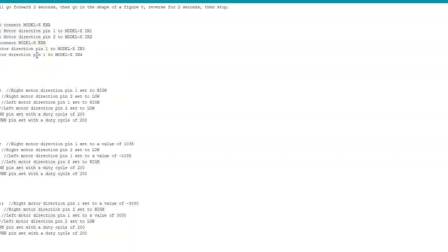That's what I'm using. The other thing you need to know is that sometimes you need drivers, just like you need printer drivers for a printer connected to your computer. You may need drivers for the Arduino, depending on your computer. A lot of times, if you need that, you would go to Tools. On my laptop, it says Update Firmware. Sometimes, like at school, it'll say Update Driver, and you would choose the driver you need for the Uno.